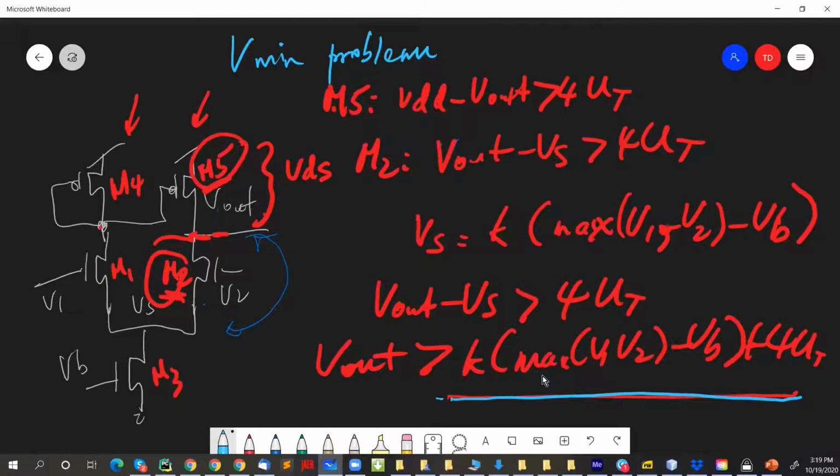So it's something you should appreciate, at least, because if you're going to use the circuits, you have to understand why you would see, for example, that V out cannot drop below ground, especially if you're going to use the circuit to drive yet another circuit. If V out becomes the V in of yet another circuit, and you're assuming that V in can move all the way to ground, then you're going to be surprised. Because here it's saying that V out will never go close to ground. So you cannot assume that if I want an output voltage that goes all the way from VDD to ground, I'm going to get it out of this circuit, because you won't. So you might want to change that circuit if that's what you're looking for.